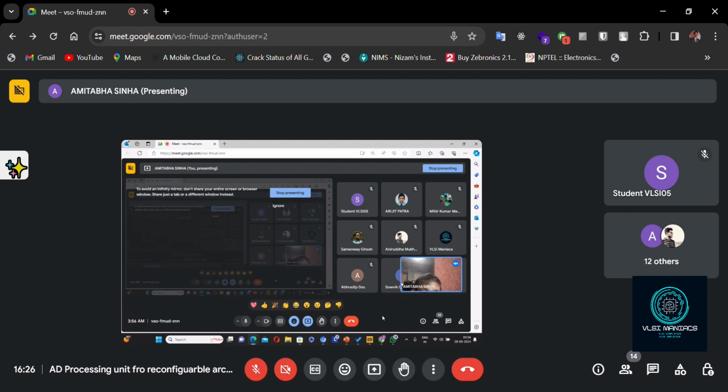In fact, I will be discussing in my next lecture how the FPGA functions totally, the hardware design. So first is configuring the FPGA. For configuring, the control unit gives a command to one controller. This controller sends the necessary signals to the serial PROM where bit streams are stored.